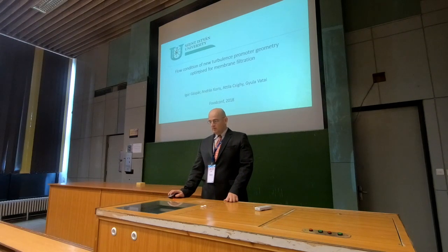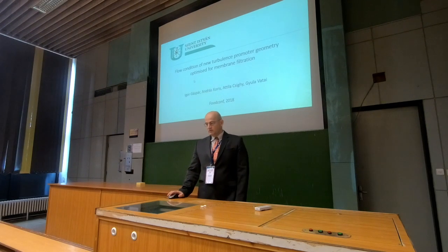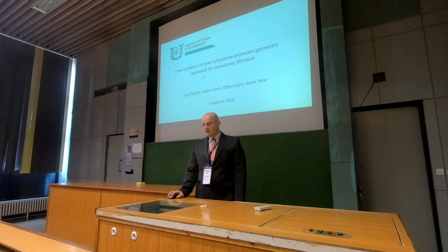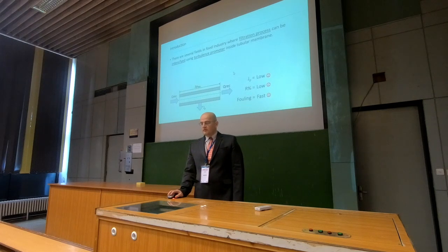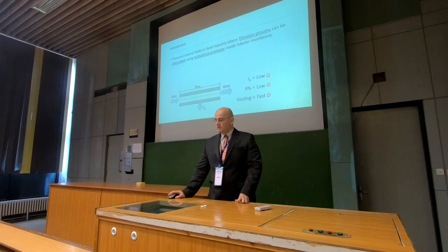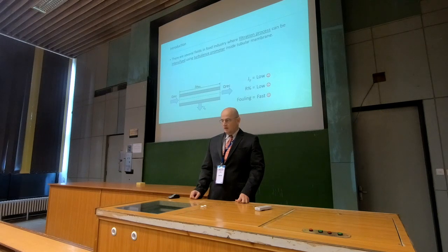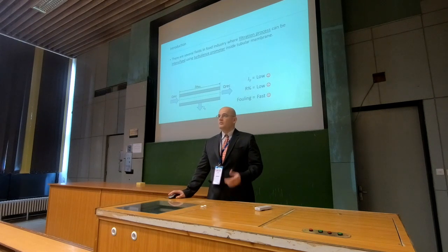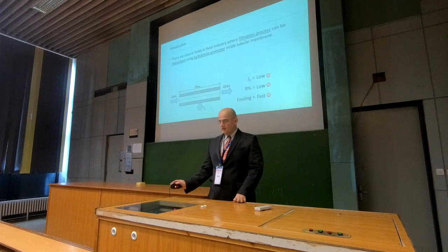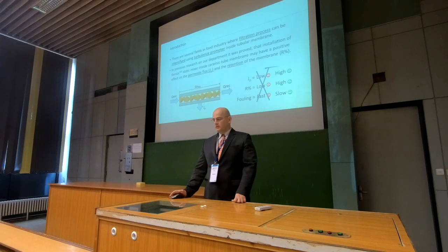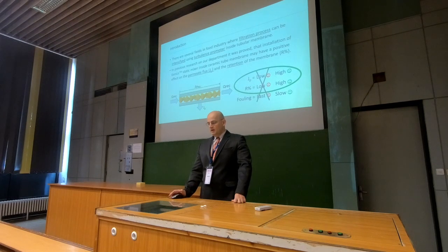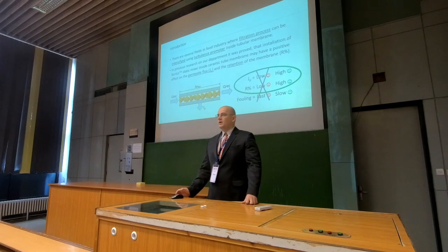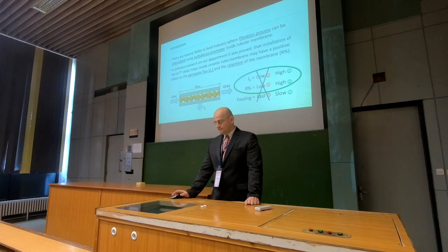Dear audience, the topic of my presentation is flow condition of new turbulence promoter geometry optimized for membrane filtration. There are several fields in the food industry where the filtration process can be intensified using turbulence promoters inside a tubular membrane. And in our earlier research we proved that using a Kenix type static mixer may have a positive effect on the permeate flux and on the retention.